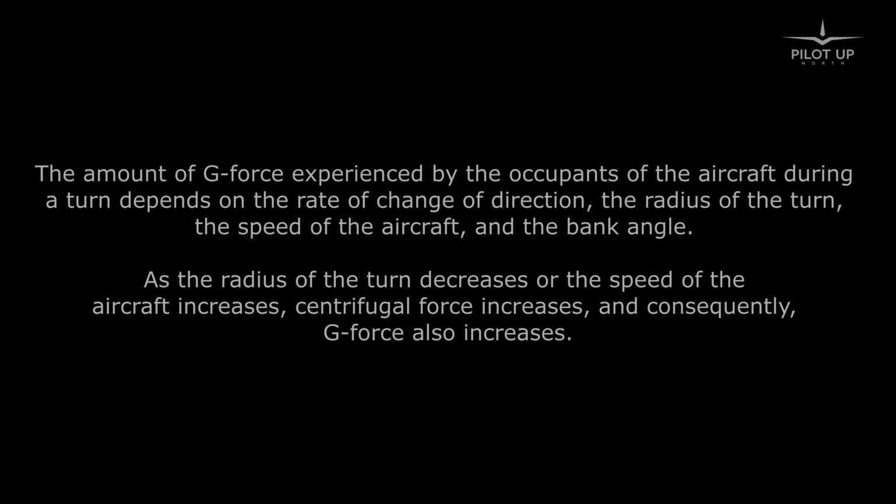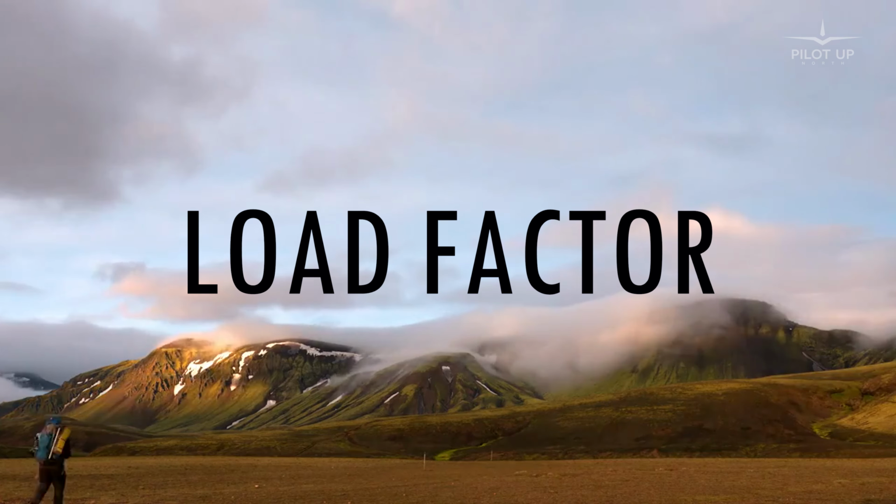The amount of G-force experienced by the occupants of the aircraft during a turn depends on the rate of change of direction, the radius of the turn, the speed of the aircraft, and the bank angle. As the radius of the turn decreases or the speed of the aircraft increases, centrifugal force increases, and consequently G-force also increases. Okay, the other force we have is load factor.